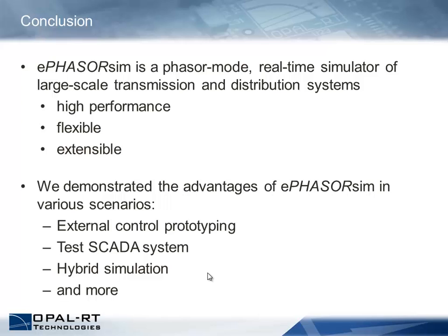Yeah, well, that we can also investigate. The problem with simulating multiple sequences is not so much simulating the sequence, but of course interfacing the sequences once you have a fault, right? So once you have a fault, if you consult the basic textbooks, they will tell you, just merge the systems, put them in series or in parallel or something like that. But what if you have two faults? Then it's not the same story. Even doing that interfacing by itself is a heavy operation to do in the context of real-time simulation.